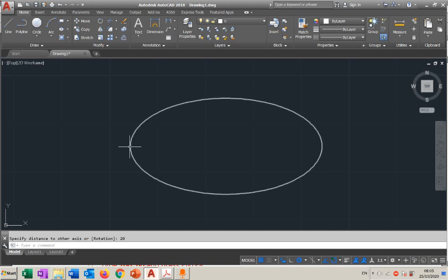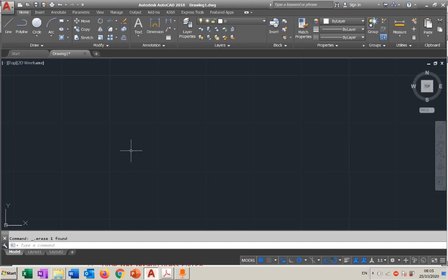But remember this one, for us in engineering drawing, when you do it on paper, it matters. It matters which one is the main and which one is the secondary. Why? Because according to that, we will set up the drawing centers. We will draw this by four centers in a hand drawing. This is the first method that we will do for ellipse.